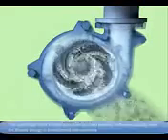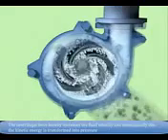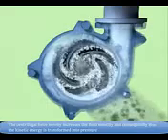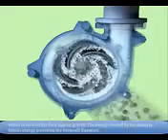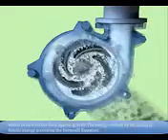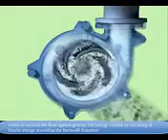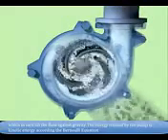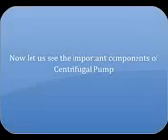The centrifugal force increases the fluid velocity, and consequently the kinetic energy is transformed into pressure, which in turn lifts the fluid against gravity. The energy created by the pump is kinetic energy, according to Bernoulli's equation. Now let us see the important components of a centrifugal pump.